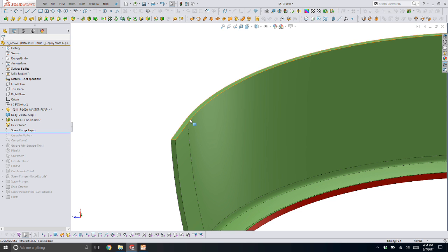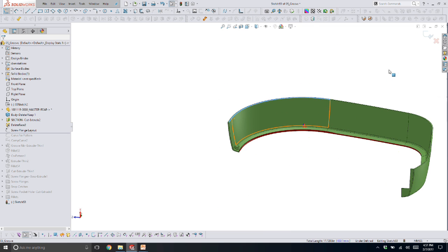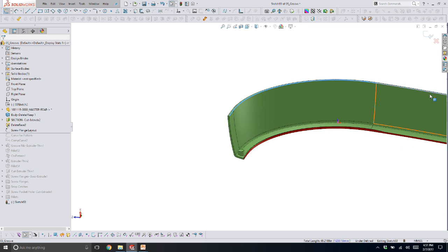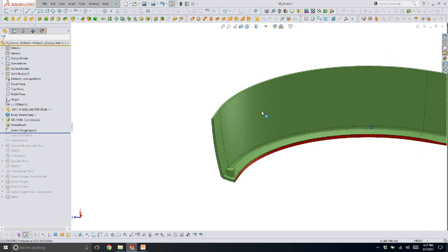So I just roll up. And then I actually put the sketch for my groove, and I usually always pick the inside edge, and I try to avoid sketch offsets wherever possible. Right-click, select tangency, grab that whole loop, convert entities. I've got it in my sketch.